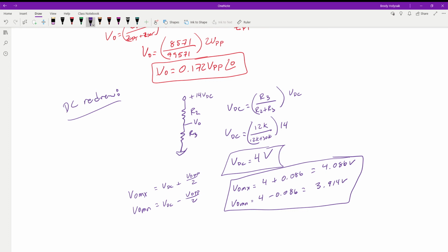You can make these assumptions, and you can remove some of the detail because for what you're doing, it doesn't matter. Another example is if you're tracing digital signals, and this is one of the things you will learn next semester as well. A digital signal, if it's considered a high or a 1, has to be over a certain voltage, and I believe it's somewhere around 3.3 volts. So between 3.3 volts and 5 volts is considered a high or a 1.